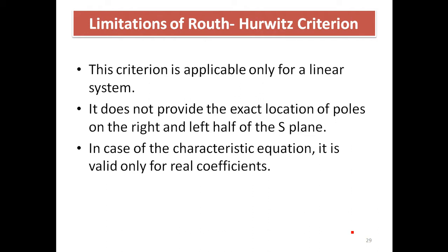If you have any one coefficient as negative in the characteristic equation, then the system is unstable. So in this way we have considered a lot of conditions where the stability of the system using the characteristic equation and application of Routh's table can be evaluated.